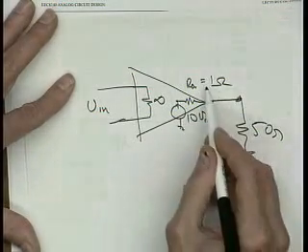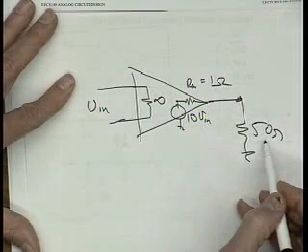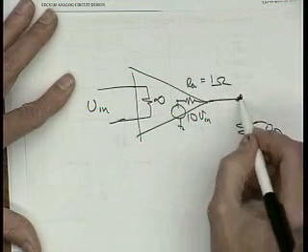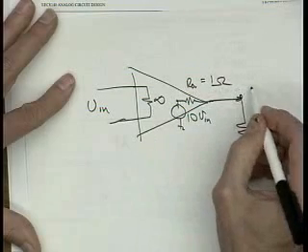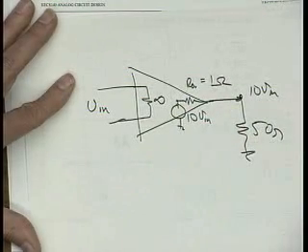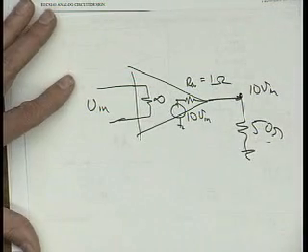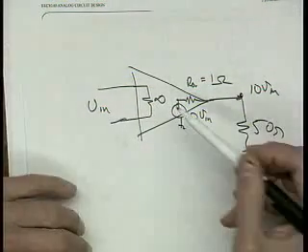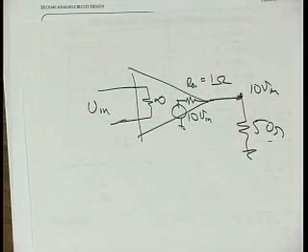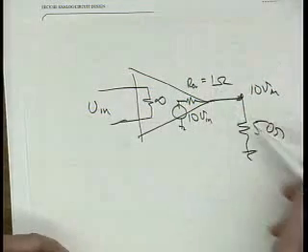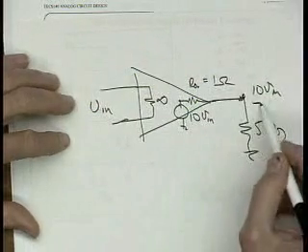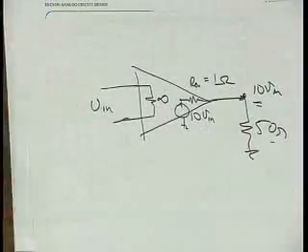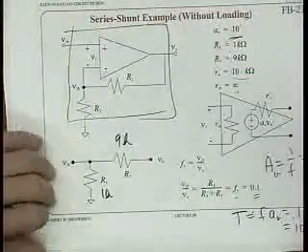So I can drive 50 ohms here, and what gain am I going to get here? It's going to be a voltage divider between my 1 ohm and 50 ohms, right? So there'll be no voltage division at all. So this will be exactly 10 times V in here, right? So this 50 ohms is a very large resistance compared to the output resistance of this circuit. Okay? If I had 50 ohms here for an output resistance, I'd lose a factor of 2 there. And I become pretty much independent. It's really set by that ratio of resistors. Okay?